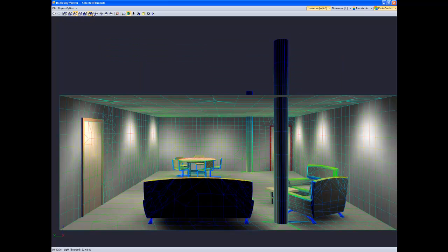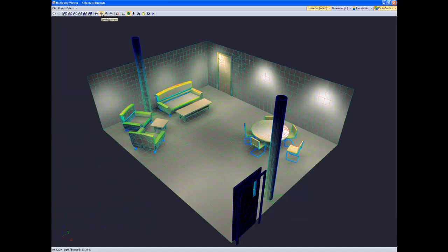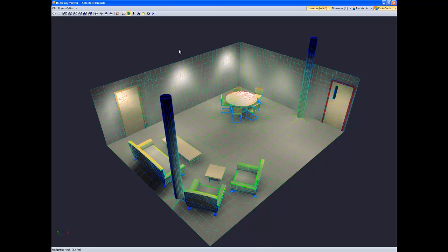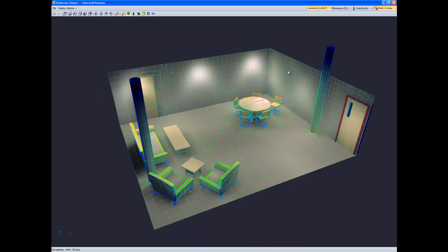After the direct light is shot, the brightest group of elements in the room become a virtual luminaire and cast their reflected light back into the environment. Each successive step projects the brightest elements remaining, and the process continues until all light has been absorbed. This is a state called convergence, yielding a completed calculation and visualization.